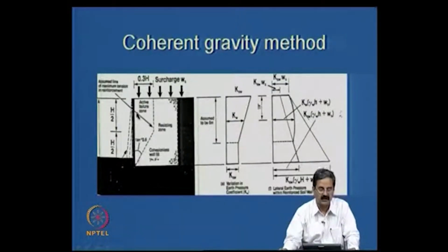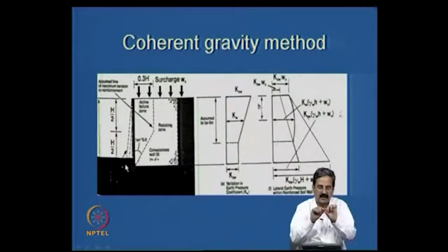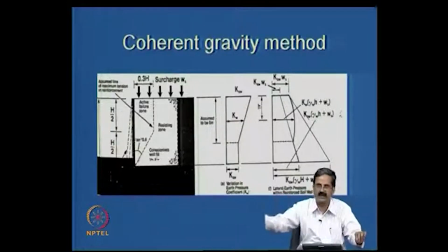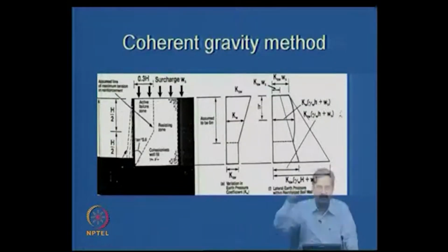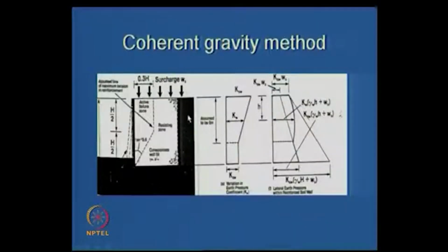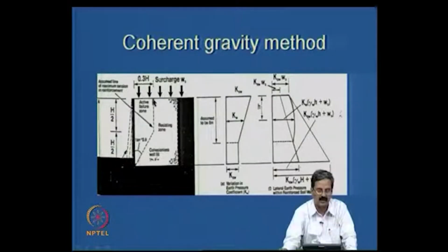If you observe all the reinforcement elements, where the maximum tension is, and locate and join them, you can find the distribution of tension on the reinforcement. As friction develops along this, there will be strain mobilization, and all these points you can join, even in FLAC or PLAXIS analysis you can get that. So this is one important method that one should understand.